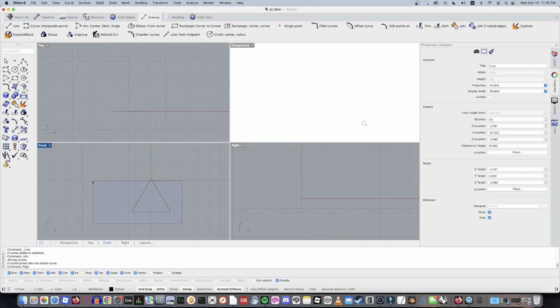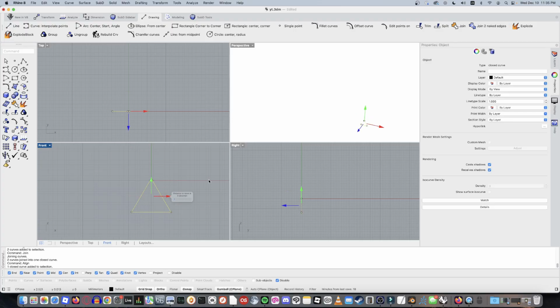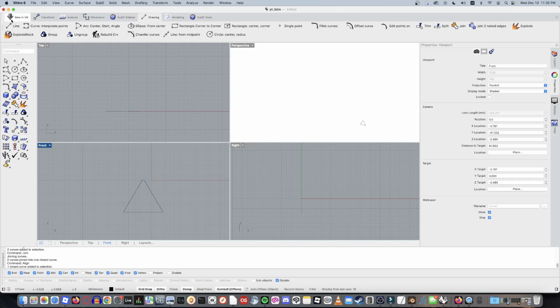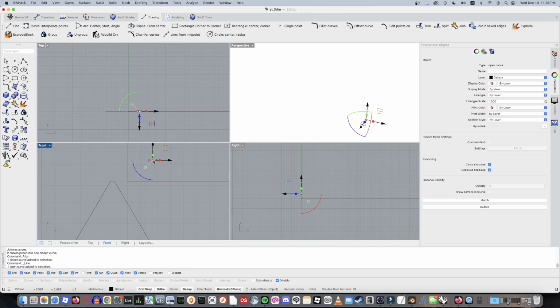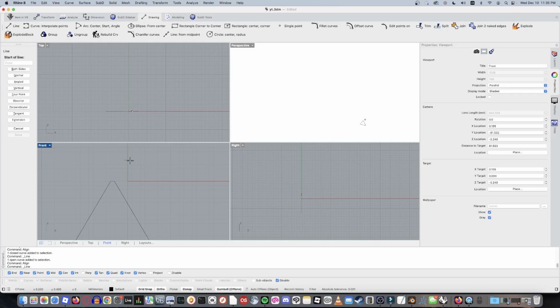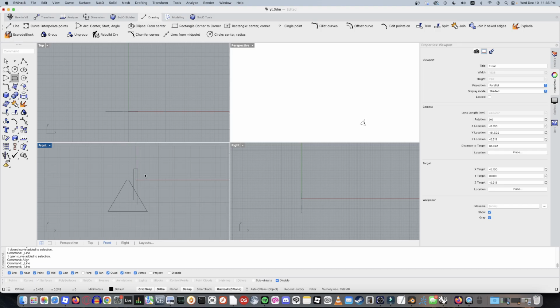and yeah, once you've done that, you can select this, move it over to the left by your thread divided by 2. Then you're going to create a line, a horizontal line. It's going to be your thread divided by 4. You're going to bring this line, align it right over to the middle. Then you're going to have 2 lines sticking down straight.